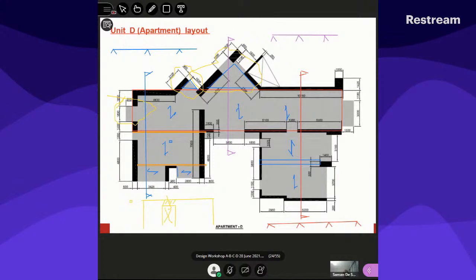So this is one with a little cantilevering part. This is simply supported. So if you then look at analyzing this, you take a 1 meter wide strip of the slab, which is being supported by these beams, and that encompasses your slab design.